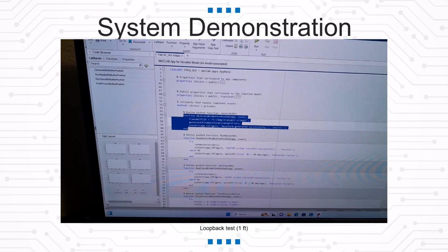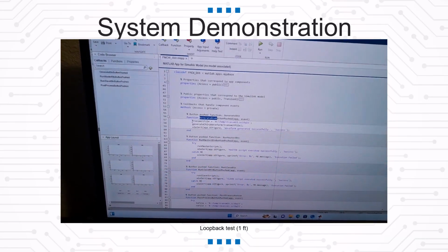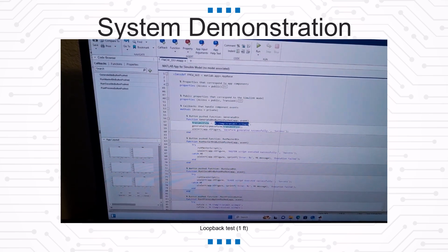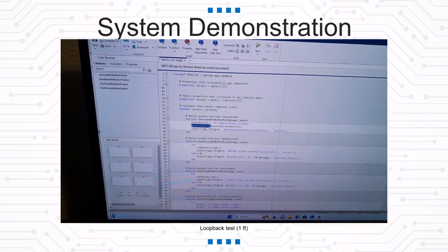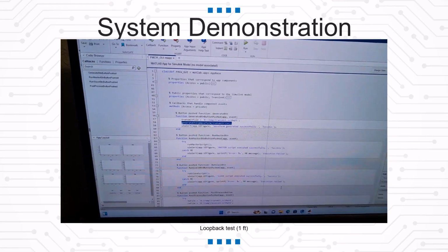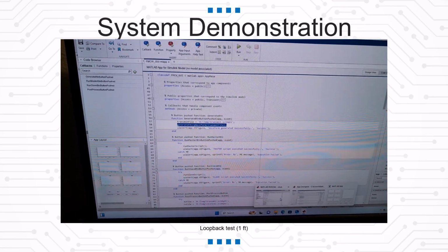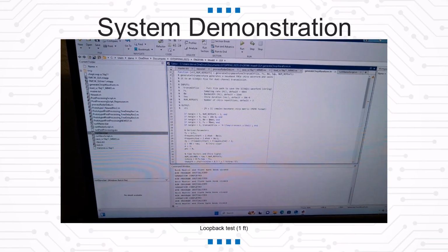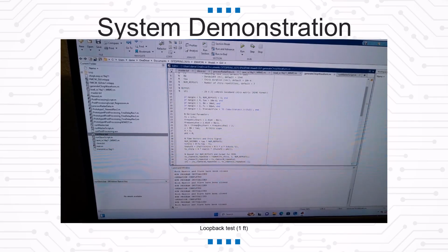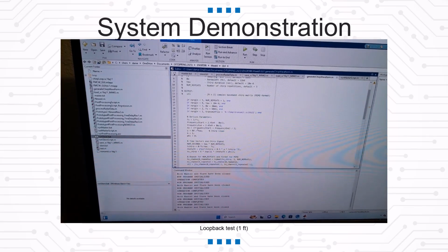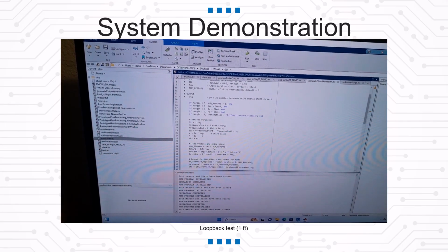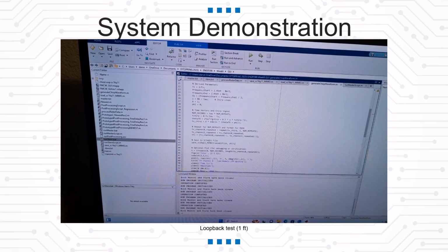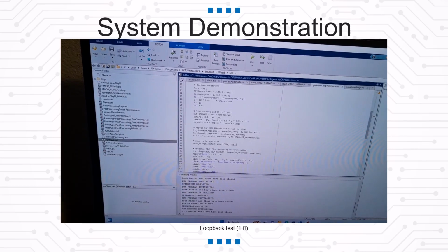So the first button is the generate waveform button. It sets the name of the transmit file, and it's taking it from digital RAM. And then it calls the generate chirp waveform function. The generate chirp waveform function is a custom function that just sets the parameters: start frequency, end frequency, carrier signal, the chirp slope, and it turns it into a 2-channel chirp.